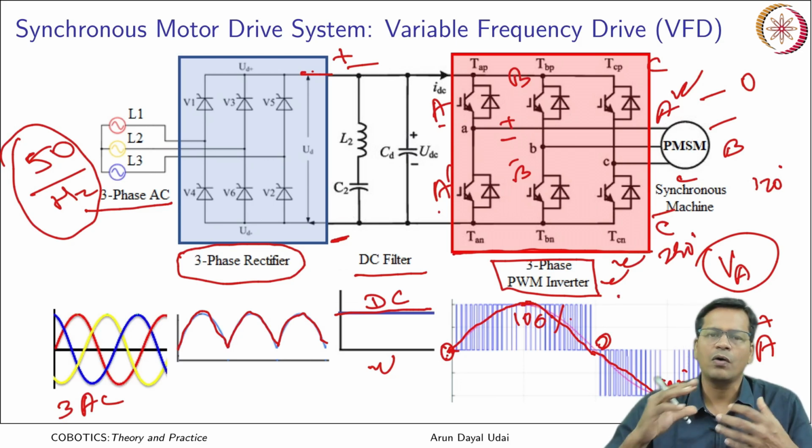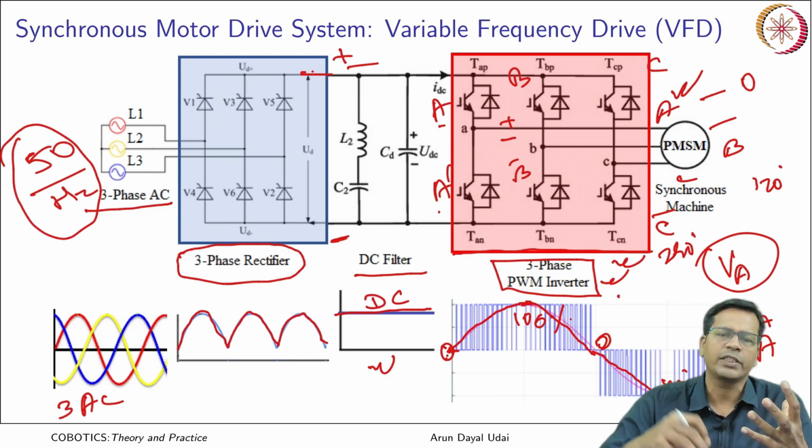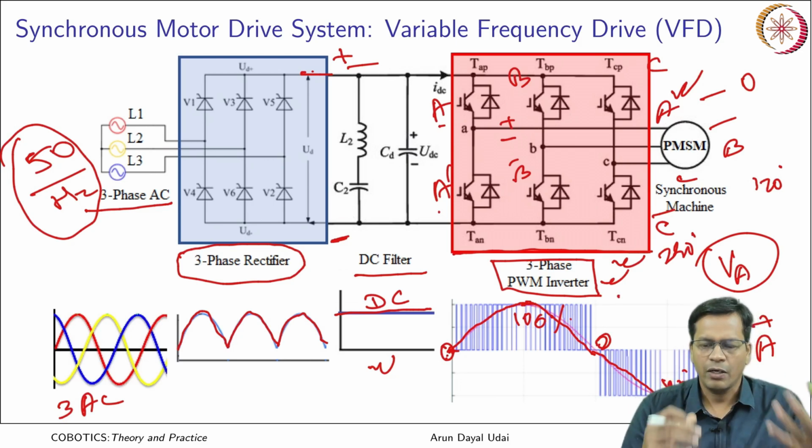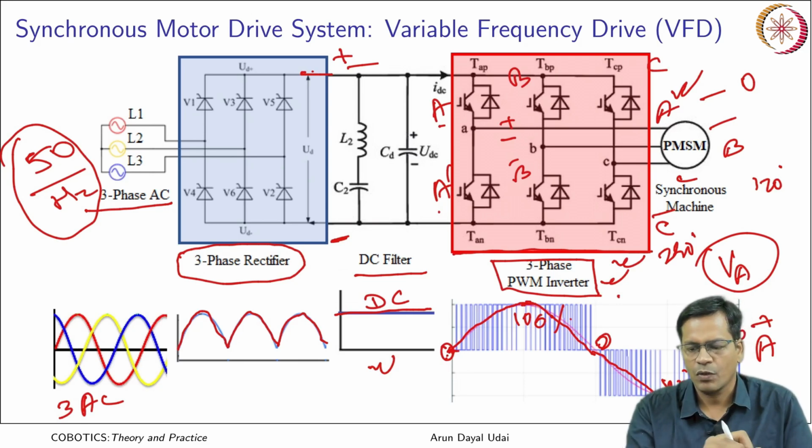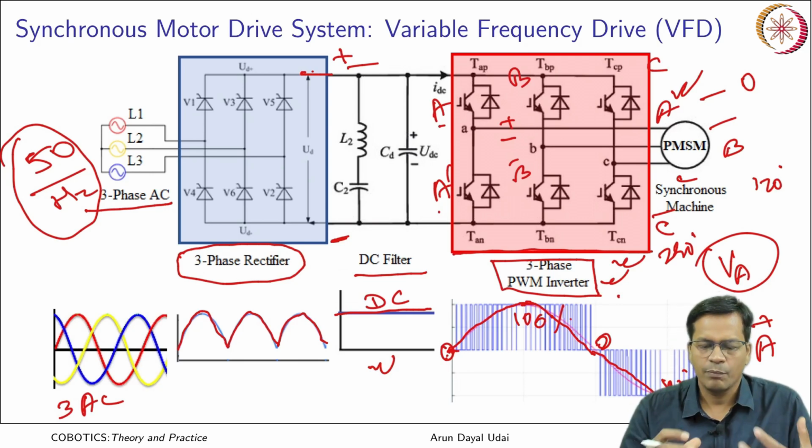So you saw how a rotor gets locked to the rotating magnetic field and how a variable frequency can be used to create a magnetic field with different rotation frequency. Okay. So, this is how this motor speed can be controlled.